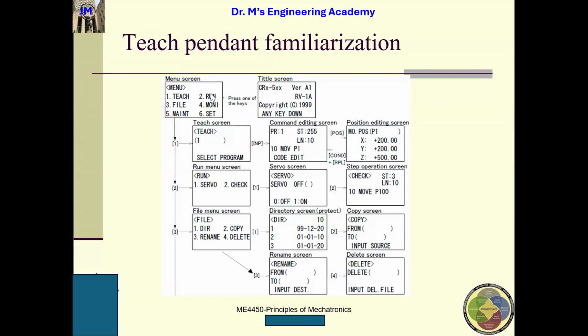And this is the program from the teach pattern. And so here are the different keys, okay? Different keys have different functions. This is the menu. So for example, this teach here, you need to select a program, and you are writing this program, okay? You can see 10 move and to P1.